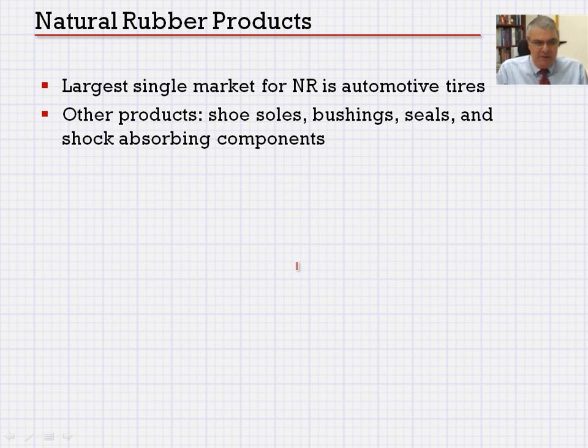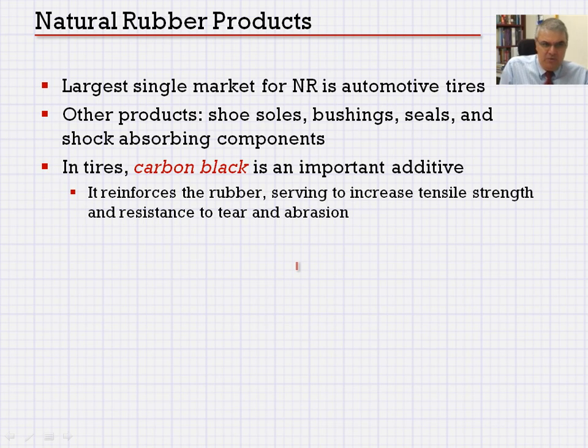They're basically chunks of rubber, but they're polymers, and they are used in larger buildings in areas of high seismic activities, and we actually put the buildings on those rubbers before those rubbers get connected to the ground. They change the frequency of shaking and make the building pretty shake resistant, or earthquake resistant. Those are not common areas.